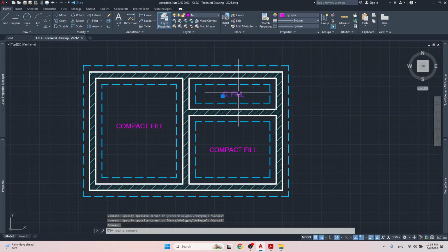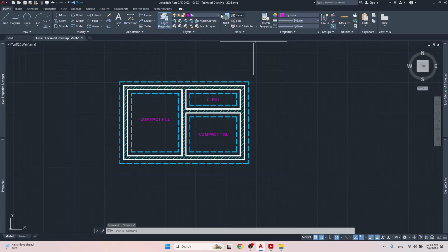If that's the case, you could turn it this way. All right. If that's the case, remember text and dimensions must be read either upright, or if you're looking at the drawings from the right side. That's the only two ways. All right. So we have that.